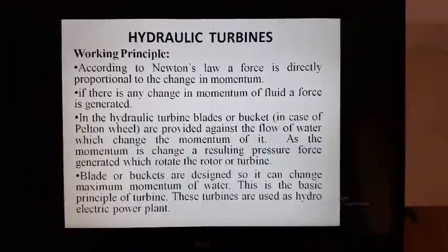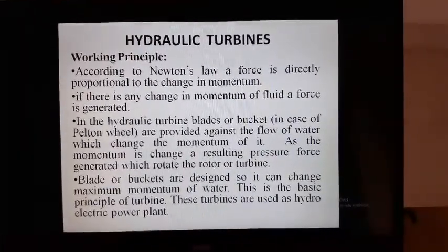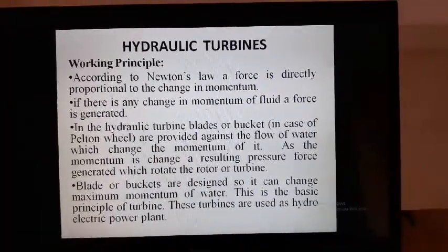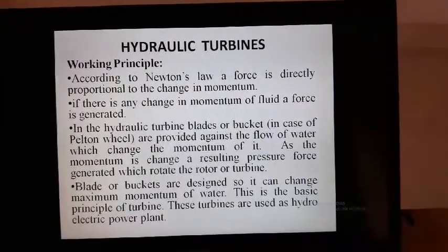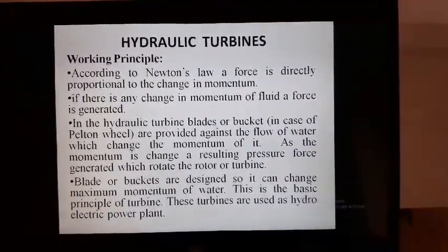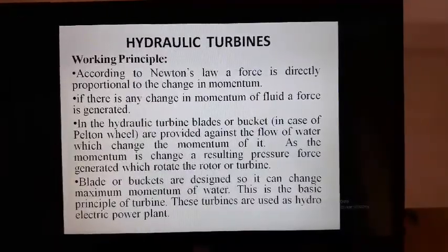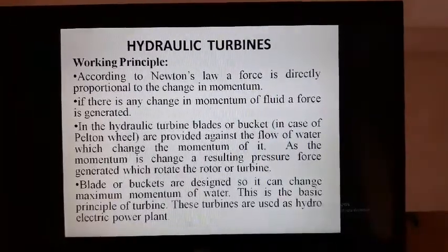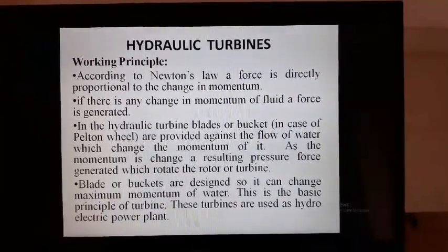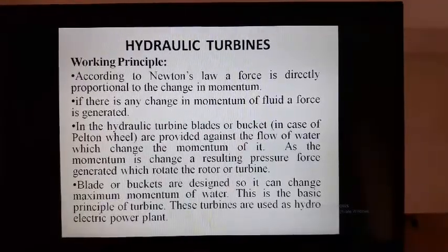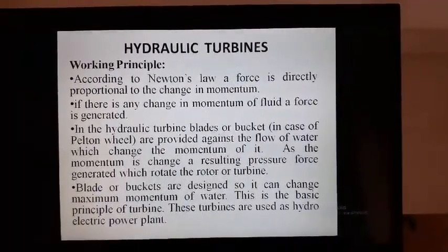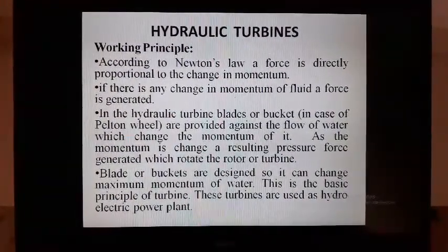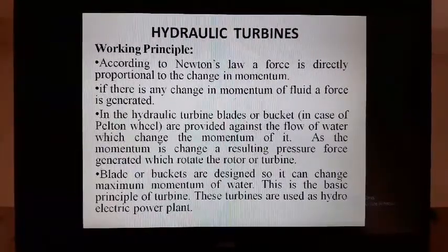Now we discuss the working principle of the hydraulic turbine. According to Newton's law, a force is directly proportional to the change in momentum. Whenever there is a change in the momentum of a moving fluid, a force is created. So, in the hydraulic turbine, the blades or buckets or vanes are attached to the rotor or runner of the turbine. The moving fluid is directed towards the vanes or blades of the turbine,